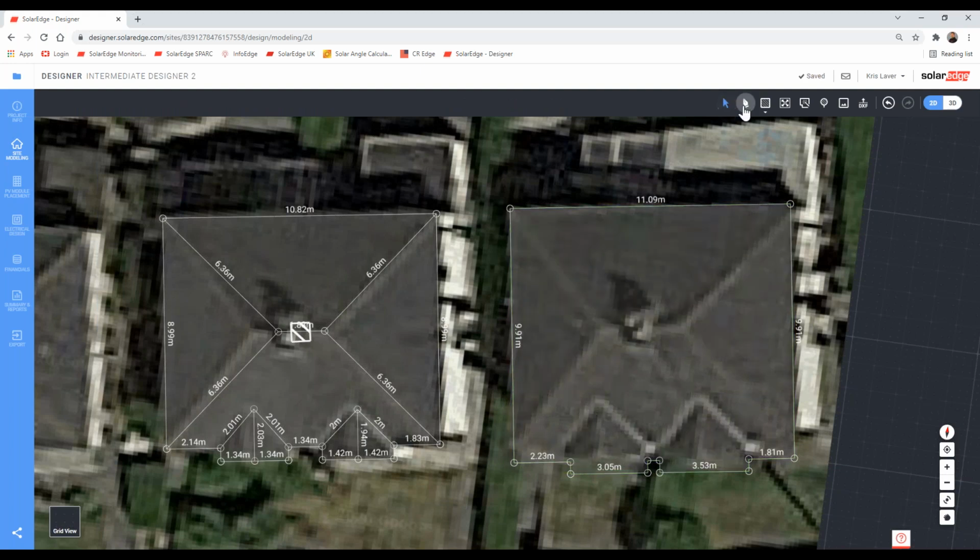Now in this instance, we've got a 4-hipped roof in effect with 2 dormers. Let's find the center point and I'm just going to float a line across there, and I'm not going to finish that line. That's just going to give me something to aim for when I'm drawing these two sections in. So I'm going to click in this corner, and I'm looking for the angle, which is those two quarter circles, and I'm going to terminate the line where it meets the ridge line. I'm going to do the same from this back corner, looking for that angle.